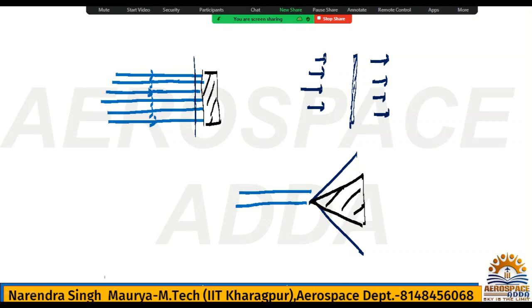Okay, so similarly here also, otherwise you may think, if the object comes inside the flow field, then how will that flow go ahead? It will stop. Practically that is correct, but to analyze the normal shock, we can say this is the object and the flow will rebound. But if you go for that calculation, you show this normal shock here, and the object obviously will not be shown there, and then you can check the property variation. Suppose here pressure is P1, temperature is T1, density is rho1, Mach number is M1, and after the shock pressure will be P2, density will be rho2, Mach number will be M2.